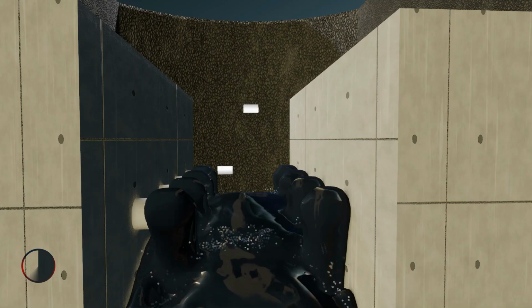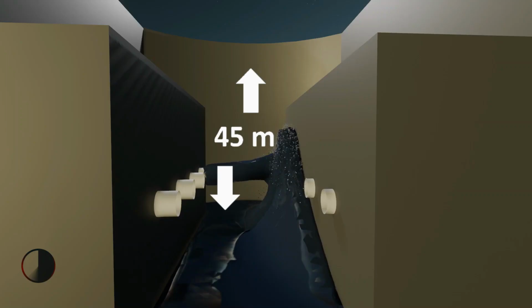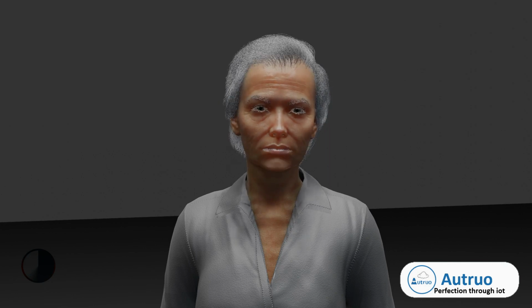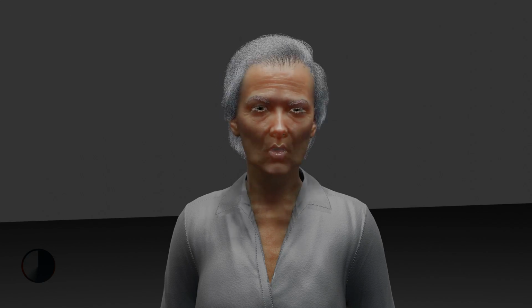What is interesting here is that two entirely different sites, one with a net head of 2.25 meters and the other 45 meters, can generate exactly the same amount of power because the low head site has much more flow when compared to the high head site with just 150 liters per second. This clearly shows how the two main variables work when calculating hydropower output. These variables are the head and the flow rate, so power output can be said to be proportional to the head multiplied by the flow.